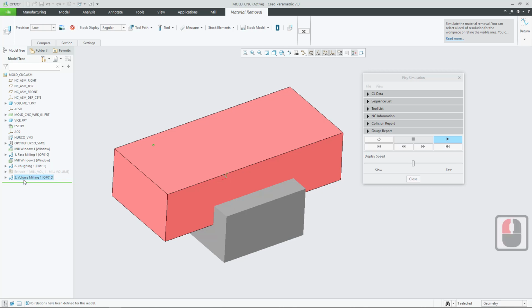And then if we press play a third time, then we can run our third milling sequence. So it's more useful arguably than having that unselected where all sequences get played automatically, and it can be difficult to see what each sequence is achieving. So let's click on play here.